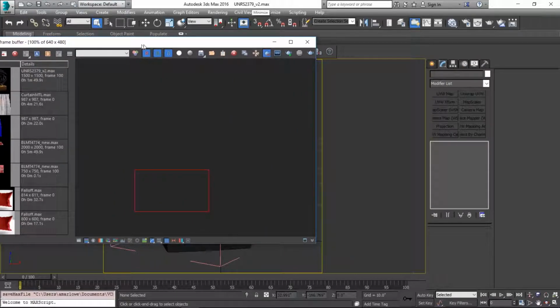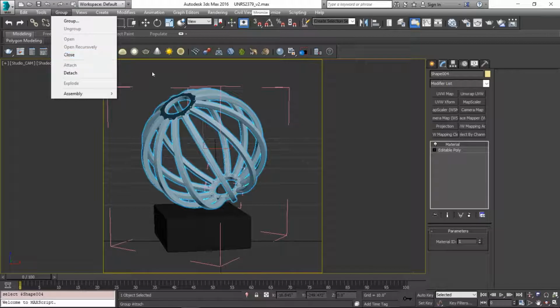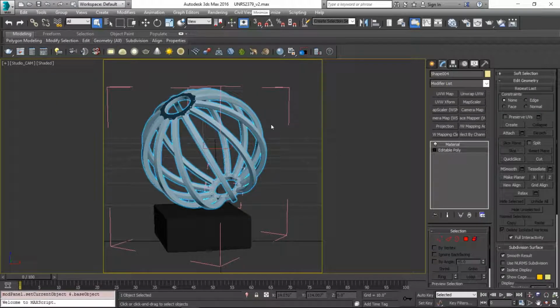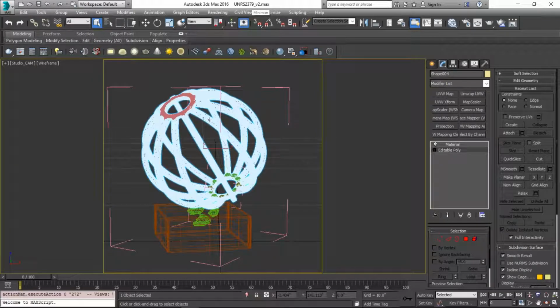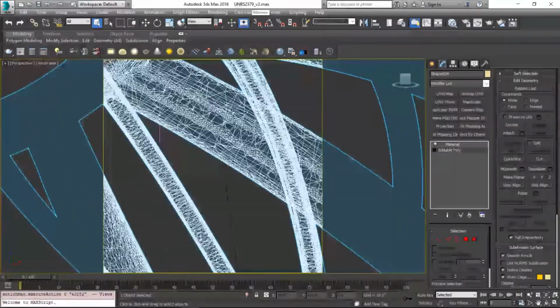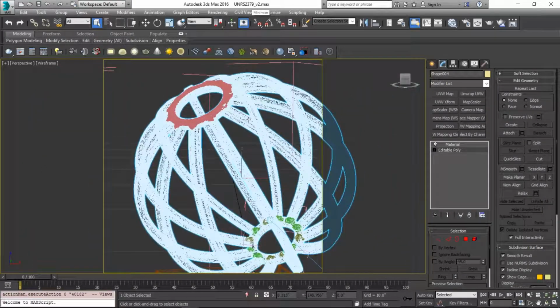So the reason why I brought that up is because this object doesn't have any UVs. It's also really dense. This would be really hard to unwrap. I didn't want to spend a ton of time unwrapping. I wanted to spend more time fixing the material. So I used triplanar texture to project all over it.